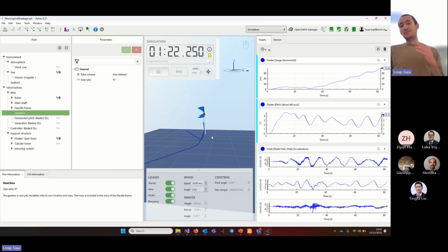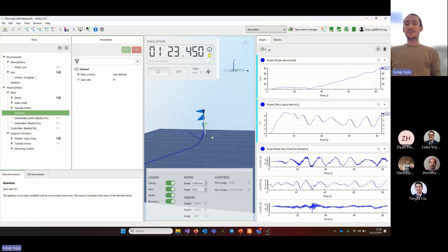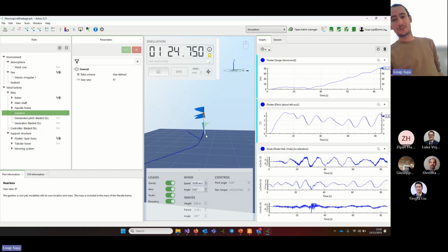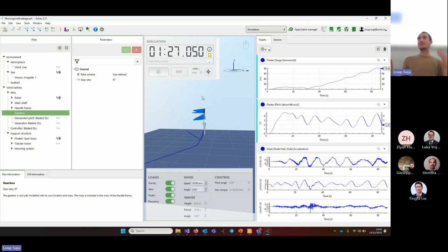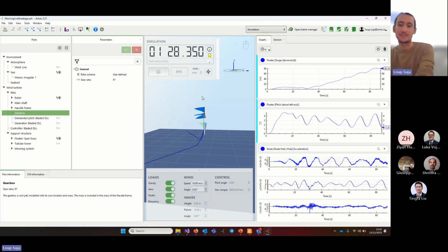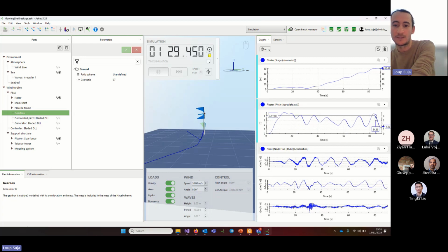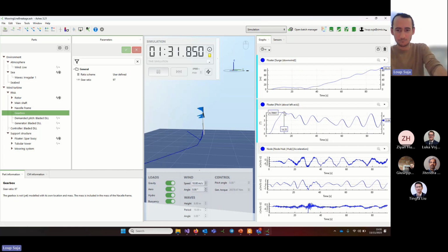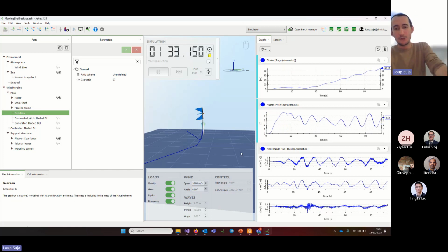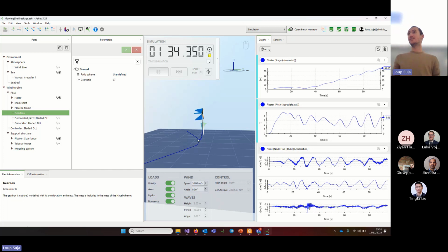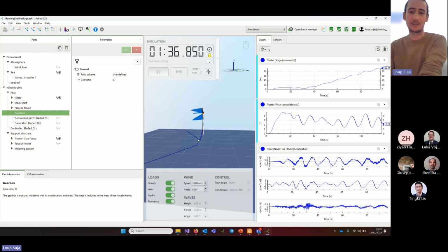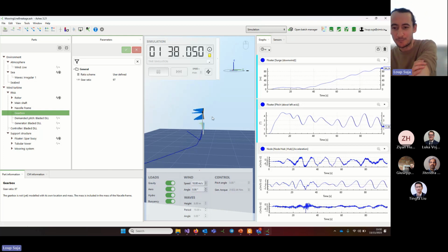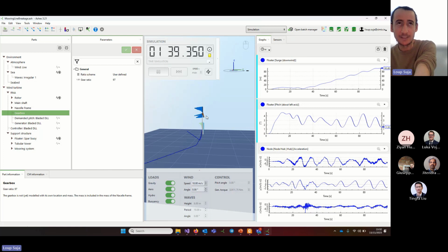So if you were to check that, there's a few things that you have to check. One of them is, this mooring line has broken now. Is my wind turbine still stable? Is it still facing upwards? This is what this graph is telling you, okay? So from here, it seems like it's not very different than before the mooring line broke. Another one would be to check the loads within the mooring lines that are left, right? So we could check the actual loads as we did before. But yeah, these would be things to check for this case.